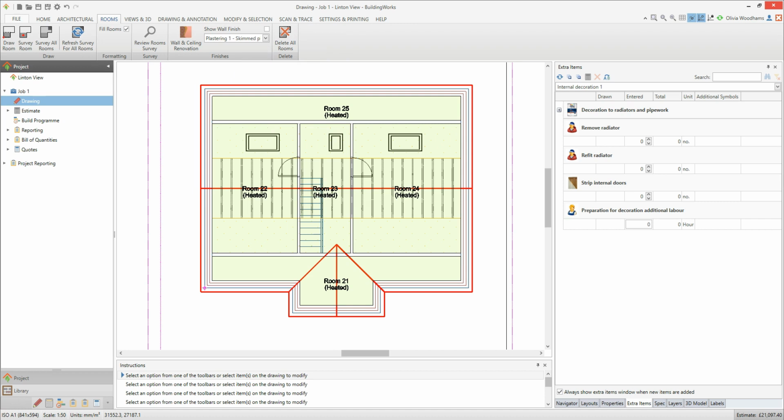Once you've drawn the existing building with non-estimated components and drawn the new staircase, copy the first floor level to create your attic level with the wall height set to 0. Then draw the attic roof, taking care to select the attic conversion option from the attic's drop-down menu. Next, draw the attic components, starting with the upstands, then the attic floor, followed by the collared ceiling.